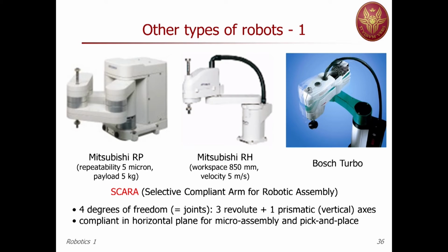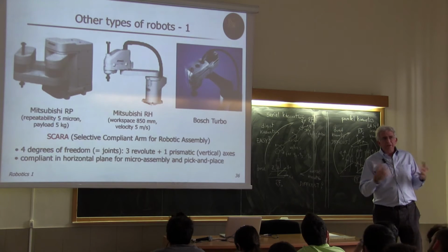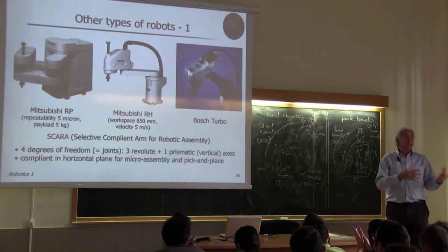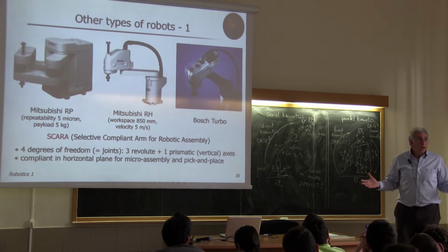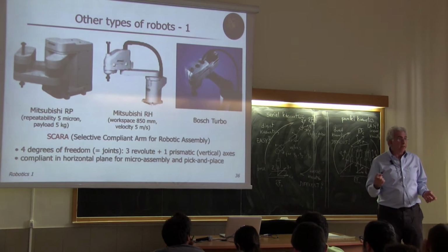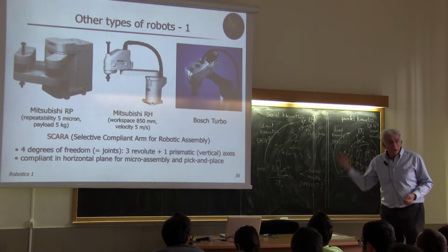And they are typically robots of the serial kinematic type, so it's a special case, with 4 degrees of freedom. Remember, every joint, which is either revolute or prismatic, provide 1 degree of freedom to the structure. So we often confuse this concept, which is more general in mechanics, of degrees of freedom, with numbers of joints, just because we handle only the case of elementary joints that provides 1 degree of freedom. So 4 degrees of freedom means 4 joints.